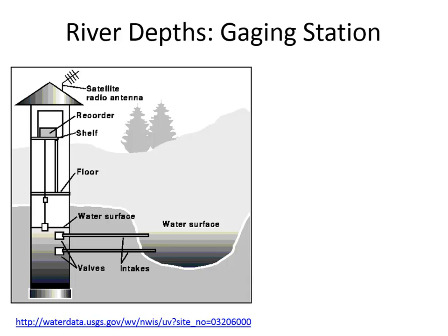And that sounds like a lot, but if you think about how big West Virginia is and how many creeks and rivers there are, it's actually kind of astonishing that the flow rate is only monitored at 150 of those locations. And so since we only know the flow depth very rarely, we have to have a process that allows us to extrapolate the known flow depth some distance upstream or downstream to be able to predict what the water is going to be doing.